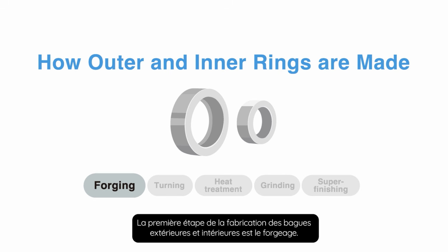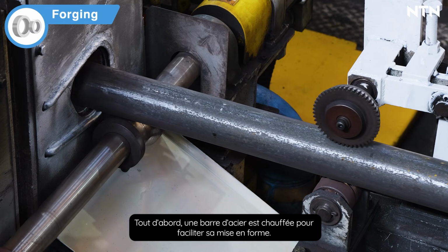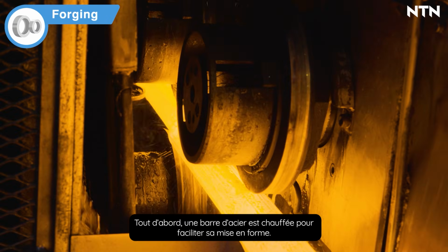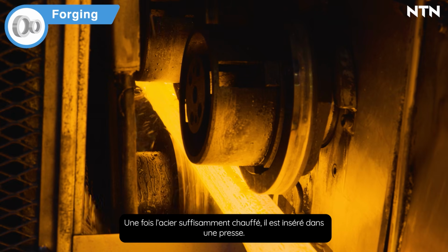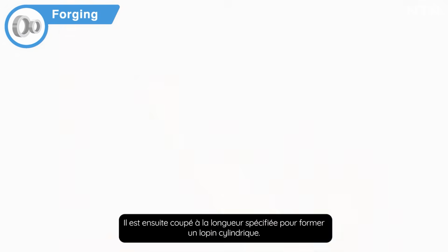The first step in manufacturing the outer and inner rings is forging. First, a steel bar is heated to make it easier to form. After the steel is sufficiently heated, it is inserted into a press machine. It is then cut to the specified length to form a cylindrical billet.